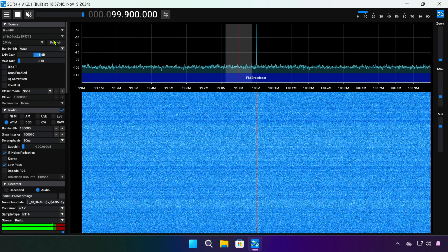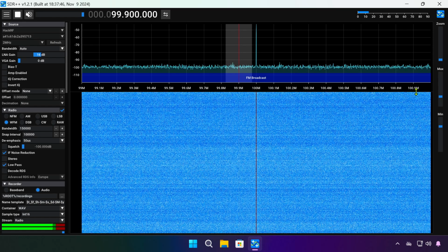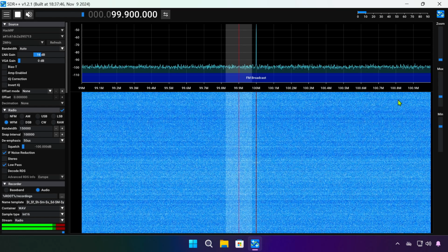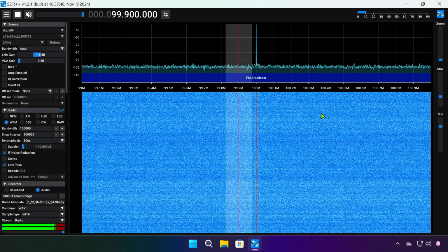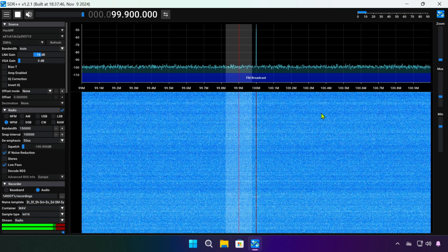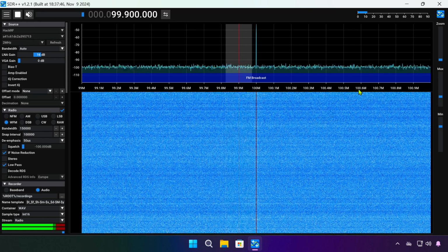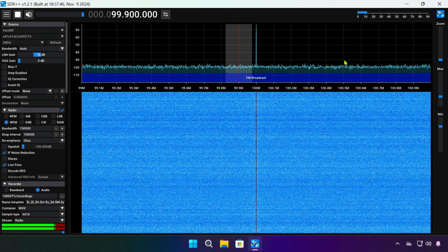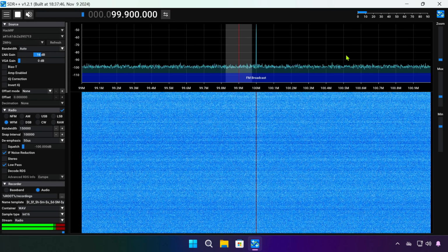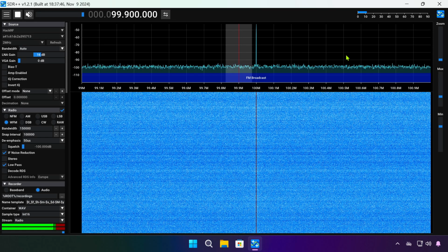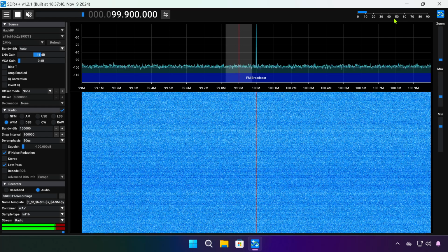And now, for example, we can also consider a practical example. Let's say your SDR receiver is designed to cover VHF from 30 to 300 megahertz and UHF frequencies 300 megahertz and above, but you're interested in listening to HF from 3 to 30 megahertz, or MF from 300 kilohertz to 3 megahertz. So this is where a converter like the Ham It Up comes in handy.